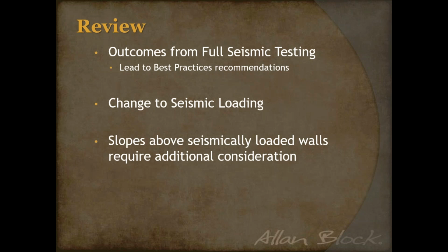And then the last thing is slopes above the wall. And I know I sound like a broken record on this, but slopes and seismic are not friends of each other. And so trying to balance those two can often lead to an engineer's headache, trying to figure out how you do a retaining wall design with a steep slope. Simplify it. Just reduce that slope by raising the grade. You might get some funny looks from counterparts, and especially your customer, but it is really sometimes your best and economical solution when you're talking about that.